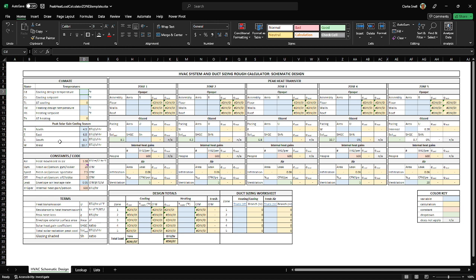In our assignment, we said 95 degrees for cooling. Now we know it gets above 95 degrees sometimes in our climate, but how many hours a year? In this design, we're saying you're just going to open the windows, or go outside, or we'll have a smaller personal air conditioner you can use. We're not going to design a whole system for every single hour because that would be inefficient.